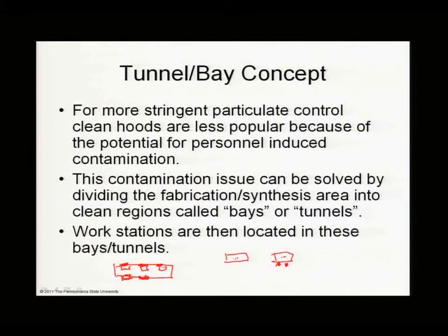And it allows more stringent particle control. Remember when we had a couple of clean hoods and we talked about taking a sample and moving it to another clean hood? Well, if we don't have a controlled volume here, then we're going to get contamination if we do that. So one way to avoid that is to define this volume, this tunnel or this bay, where we control the environment and we're able to move samples from one workstation to the next workstation. So it gives us stringent particle control,